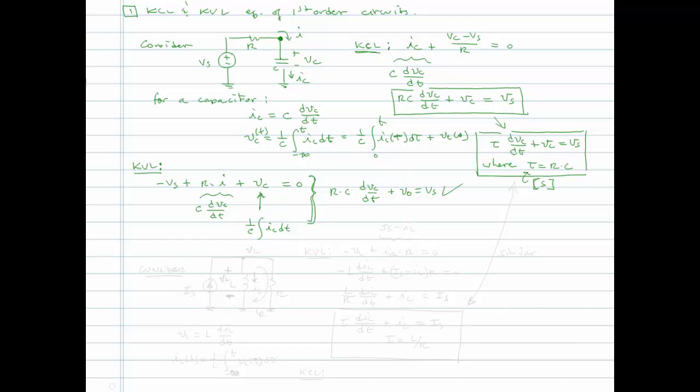Okay, and an easy way to remember this is that when you think of a capacitor, you know that a capacitor stores energy, and the energy of the capacitor is determined by the voltage across the capacitor plates, really the electric field, but it's represented by the voltage, and the energy stored is 1/2 CV squared. So for whatever type of element you are working with, in this case a capacitor, if you recognize that the energy state of the capacitor is related to the voltage, then you want to make a mental note that what you want to end up with is derivative terms in terms of capacitor voltage, okay? That quantity that determines the energy state in your system. So for a capacitor, that's voltage. We'll see for an inductor, it's going to be current, okay?